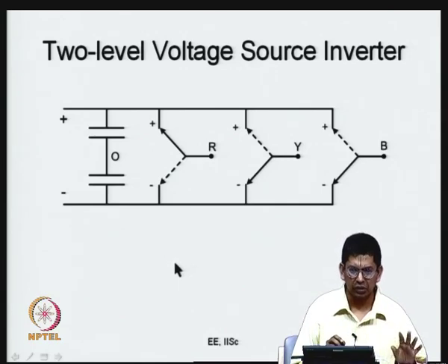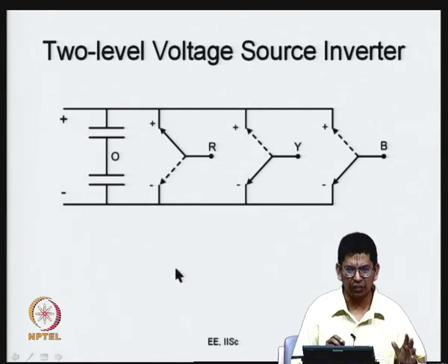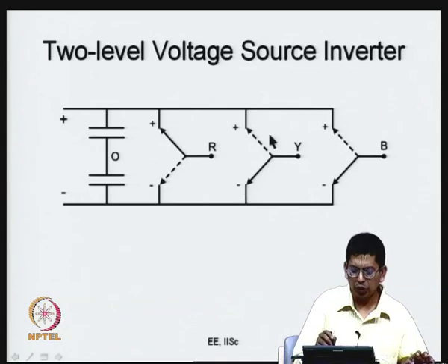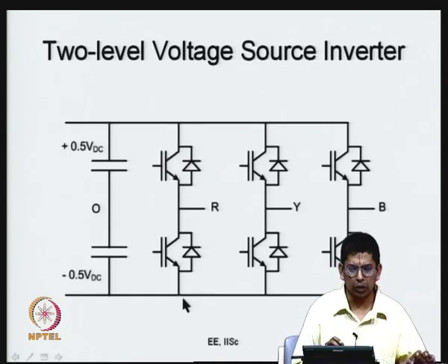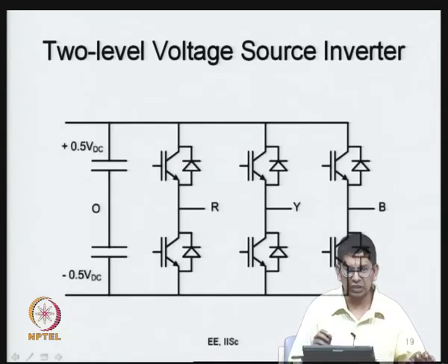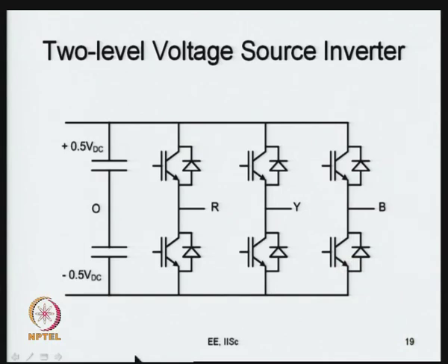It has great theoretical and practical significance. So, we just prepared ourselves by going through single phase inverter which has only 2 legs before we tackle the problem of 3 legs now. So, you have 3 legs and all the 3 are single pole double throw switches, and they are realized in terms of switches which switch in a complementary fashion as we know.